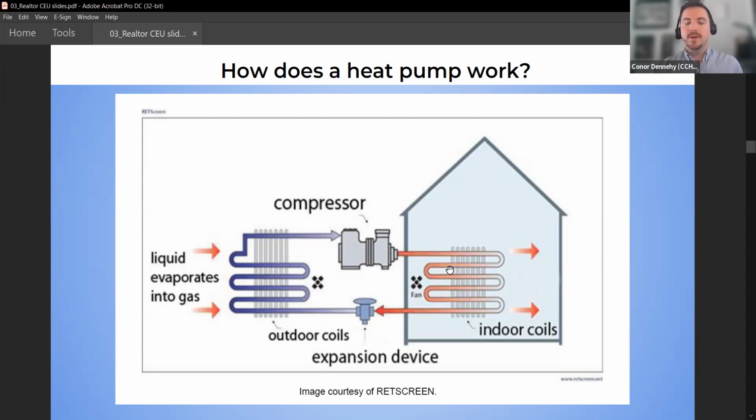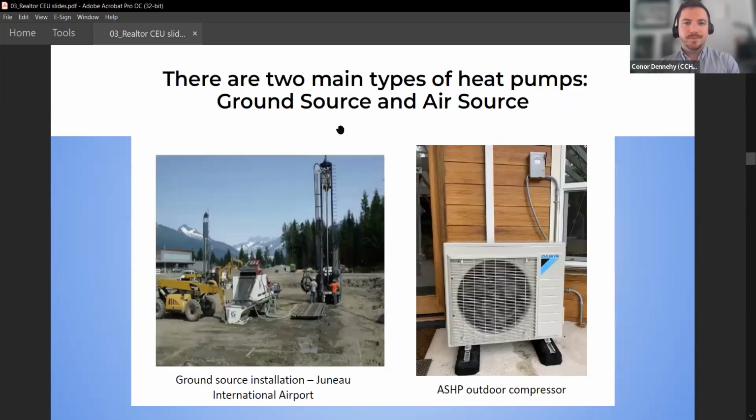And the unique thing about a heat pump is that seasonally, this whole cycle basically can reverse. And so you can imagine this would be cold, and then we're distributing heat into the outside. And we won't really have the issues here in Alaska, but similarly to how there is a kind of cutoff for cold temperatures, there's also a cutoff for hot temperatures. So there's only so much heat you can dump into the air when it's like 100 something degrees out. So heat pumps or air conditioners in general, they all have limits on either side. And so just knowing that they're not a perfect machine really helps manage expectations for them.